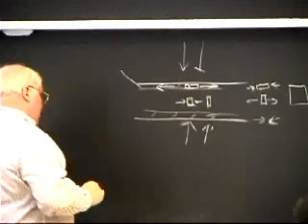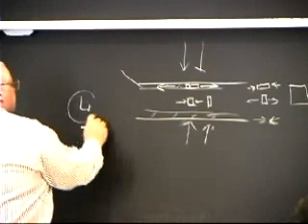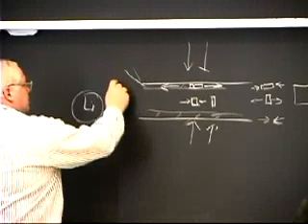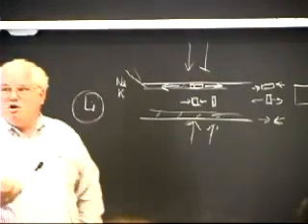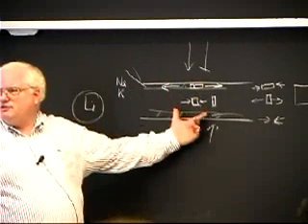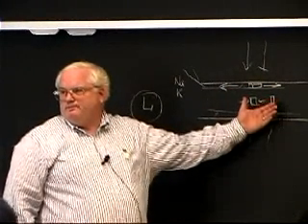With chemically tempered glass, you basically take a glass that has lithium in it, and lithium is a small ion, and you chemically exchange the lithium with sodium and potassium, which are larger atoms. And so you stick heavy atoms in on the surface, and that puts compressive stress in. Okay?